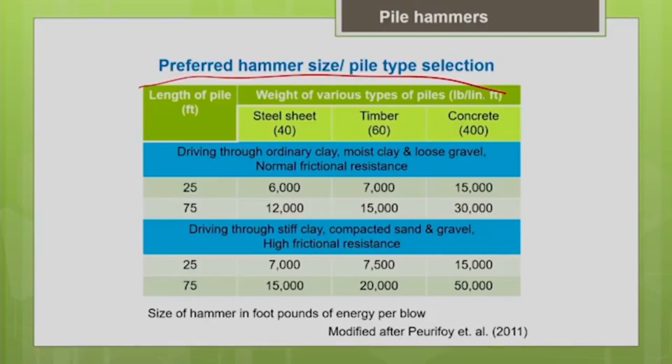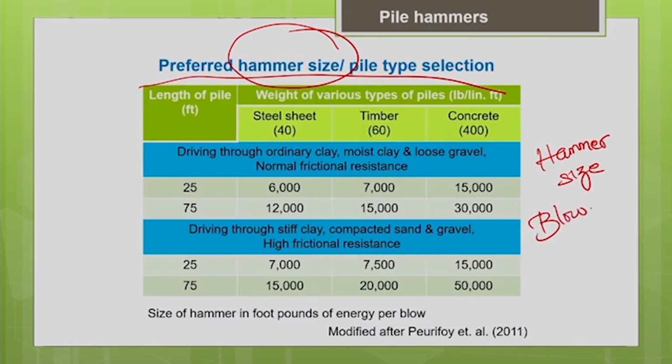Next is how to select the pile hammer based upon the weight of your pile, the length of your pile, and the material type. So, here we are going to select the hammer size. Hammer size is generally defined in terms of blow energy.